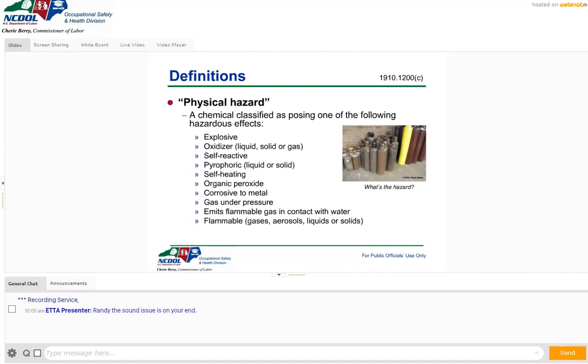And remember that the classification of combustible liquid is pretty much gone. Combustible is kind of like a descriptor now, but we used to categorize something as a combustible liquid. Fuel oil number 2, diesel fuel, those used to be considered combustible liquids. Now all of them are different classifications of flammable liquids.